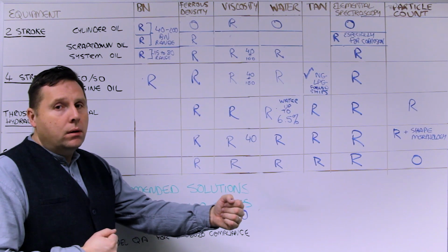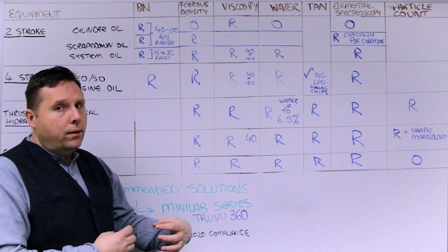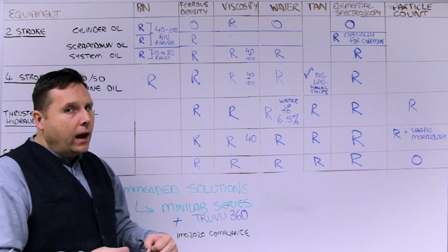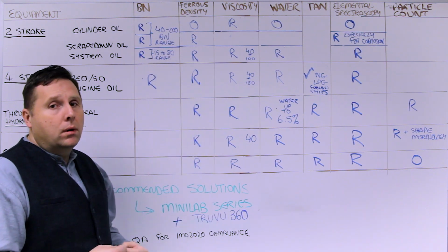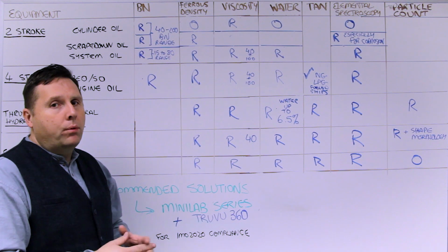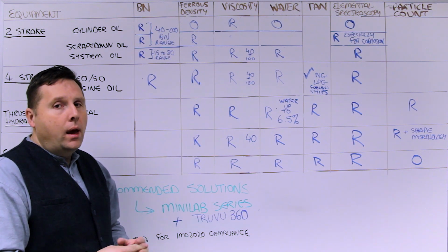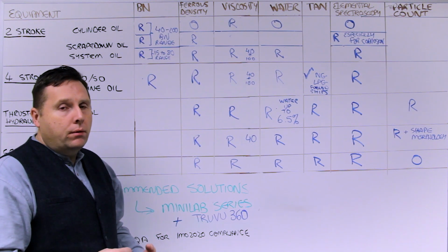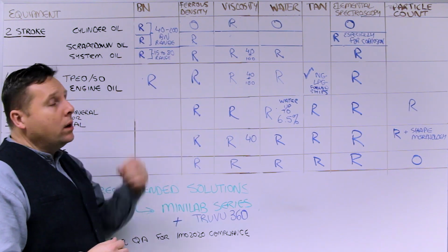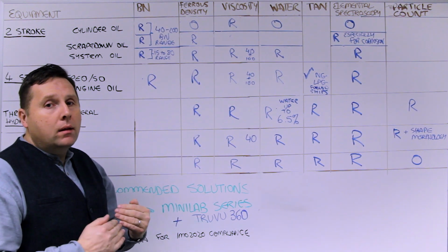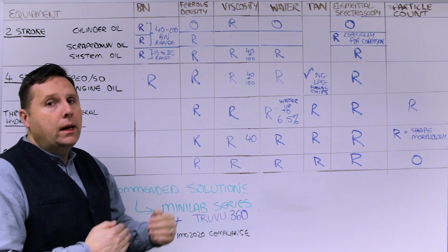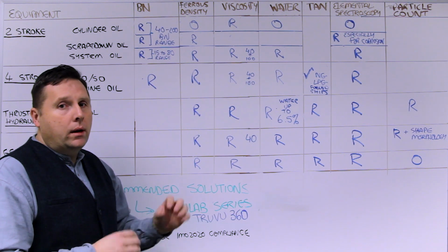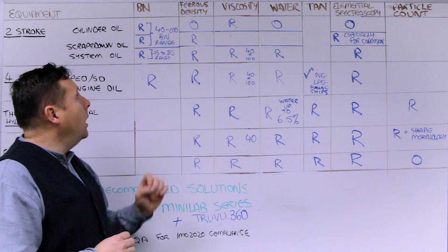And you should always be looking at those on a continuous basis, both on the incoming lubricant, if it's coming right out of the bunker, or if you have a blending on board system where you have added system oil or waste engine oil and added an additive package to bring up the base number, you want to monitor that before it sprays onto the cylinders. Once it comes off the cylinders and it drips out on the residual drain, you want to be keeping an eye on that. The base number, if it changes dramatically, indicates the level of sulfurous fuels and what's going on and the flow rates.